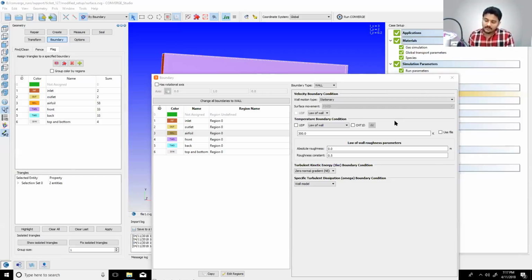To put it in simple words, in the process of discretization, we are ignoring some terms, correct? For example, to compute the slope, we are ignoring the higher order terms. Because of this error, your solution of the system is going to be sensitive to the computational mesh size and also to the time step size.